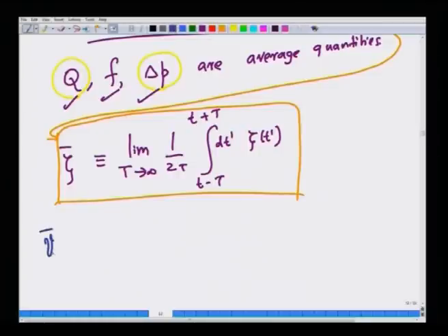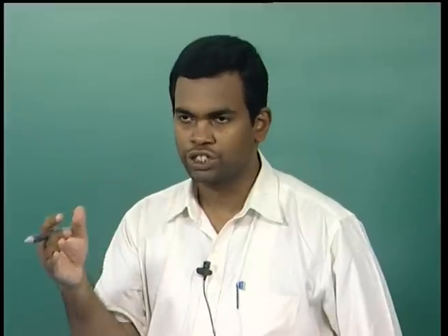So, for example, along these lines we can define the average velocity in the x direction of a flow. Once you do the time average, it becomes independent of time, because we are now considering only quantities that are stationary processes, turbulent flows where the average quantities themselves do not depend on the running time small t.